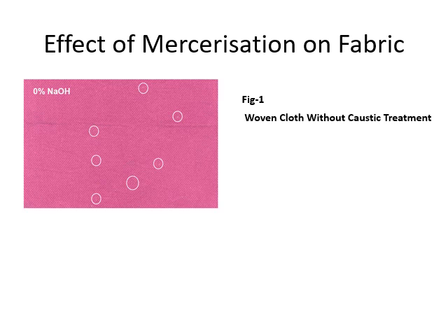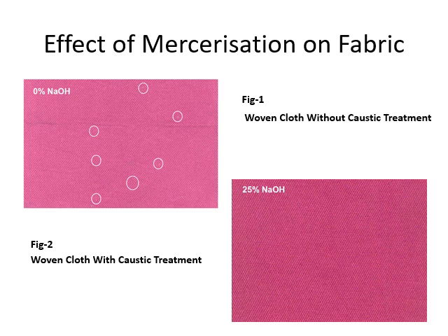In figure 1, in the white circles, the dots are there, so those are the dead cottons. Mercerization is the only process commonly used to remedy problems resulting from immature fibers. The same fabric, when it is mercerized, will not have any dead cotton, so the fabric depth is also higher, and at the same time the dead cotton white spots will disappear.